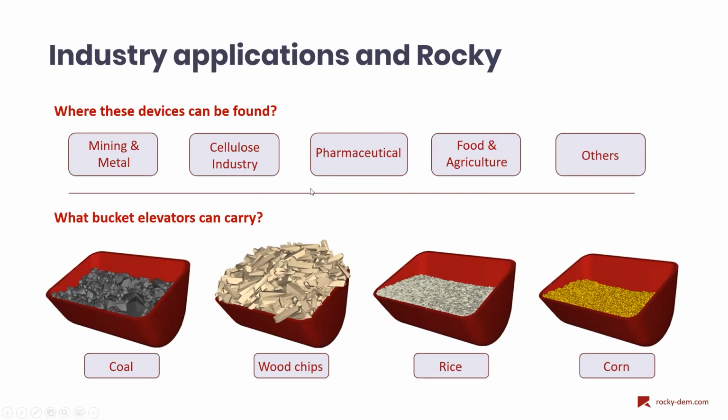And in industrial applications, it is expected that bucket elevators perform with high transportation capacity, with high translational speed, and without damage throughout the transportation cycles. This way, we can obtain the best performance for a bucket elevator without having excessive damage and misalignments. And with these objectives in mind, we can optimize these devices through DEM simulations in Rocky and also obtain crucial information about equipment power consumption, wear on the bucket surface, and total efficiency.